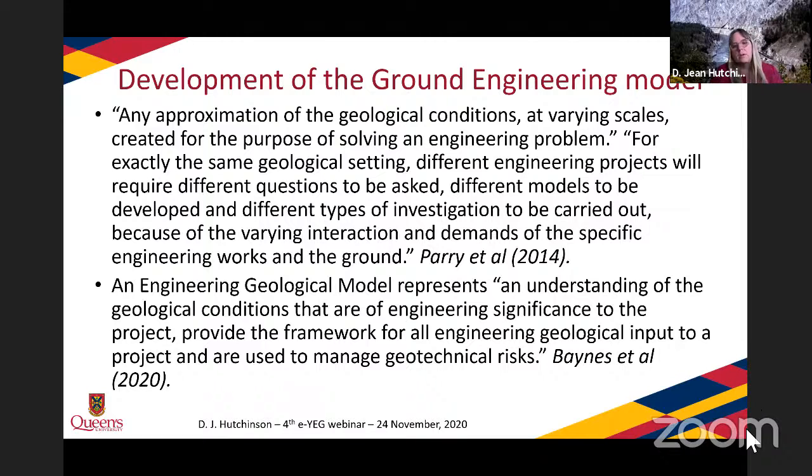So one of the ways we can help with these challenges is developing a ground engineering model. And I've put 2 quotes here that I think are really useful to explain the idea of the ground engineering model. The first is by Perry and others in 2014, and they said, any approximation of the geological conditions at varying scales created for the purpose of solving an engineering problem. So that's why you develop the ground engineering model. And they say for exactly the same geological setting, different engineering projects will require different questions to be asked, different models to be developed, and different types of investigation to be carried out because of the varying interaction and demands of the specific engineering works and the ground.